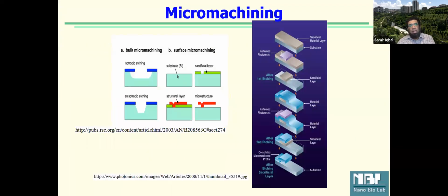Now, we use the same procedures and ideas that we talked about in nanofabrication. We make patterns, we grow oxide, we remove material, we add different materials, metals, semiconductors, a whole bunch of things. Same concept, same processing steps involved. But it is you and I who would make a recipe for our design. For example, in the right-hand picture, first I put a sacrificial layer, I pattern resist, I remove it. So we decide how we want to do it and what we want to achieve.